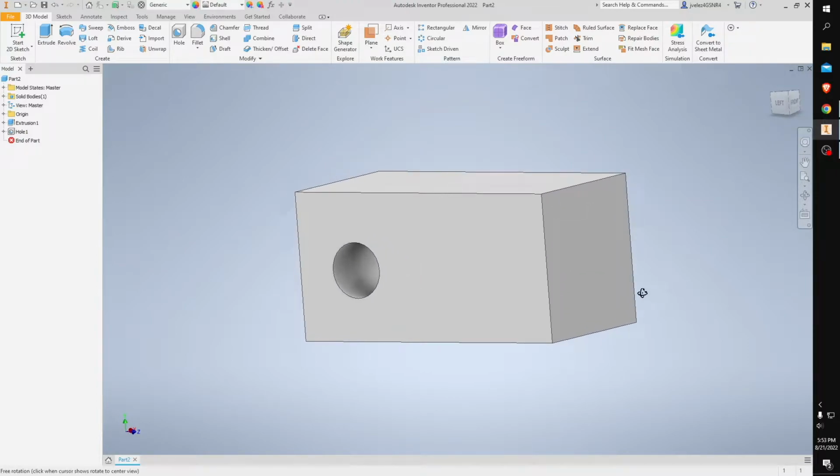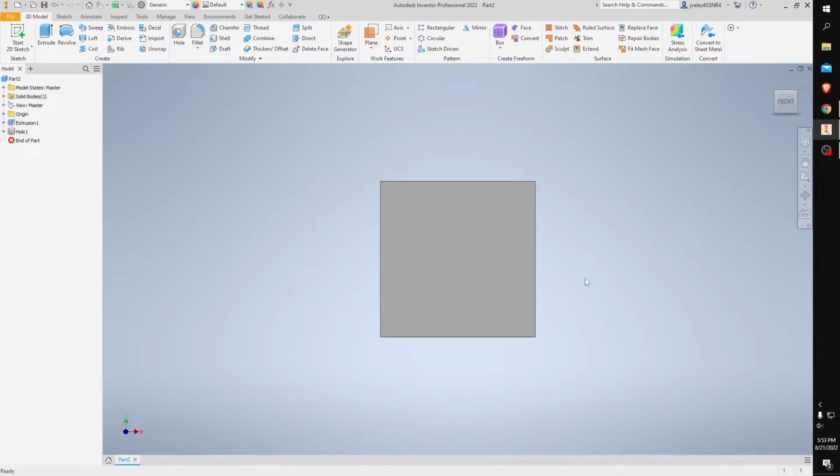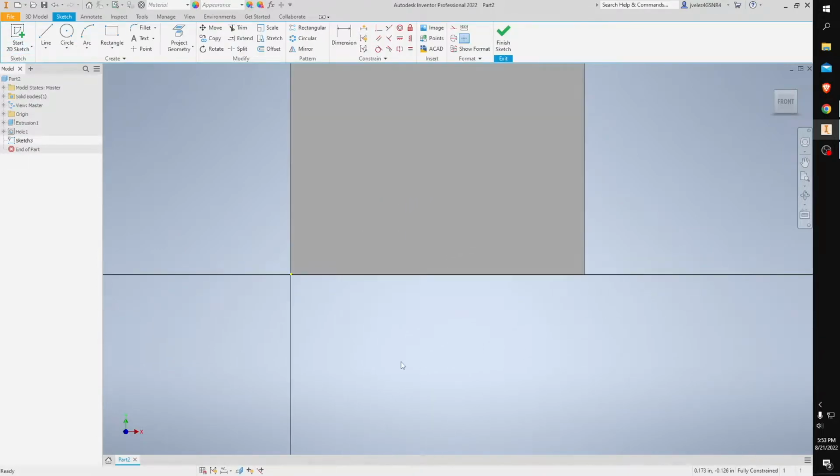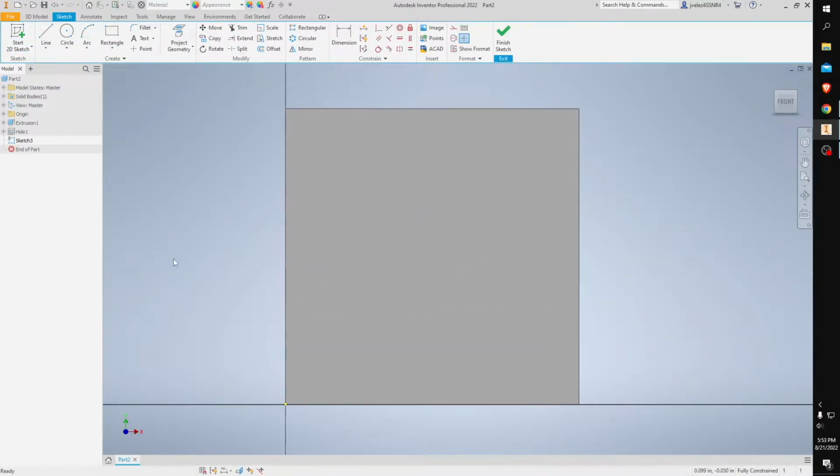Now, in order to create the stairs, we're going to use the extrude command. So I'm going to go up to the front. Here I need to sketch 2 lines in order to extrude each smaller rectangle. I'm going to start a new sketch, and this will be for this part. Here I'm going to pick 2 points and start my lines.